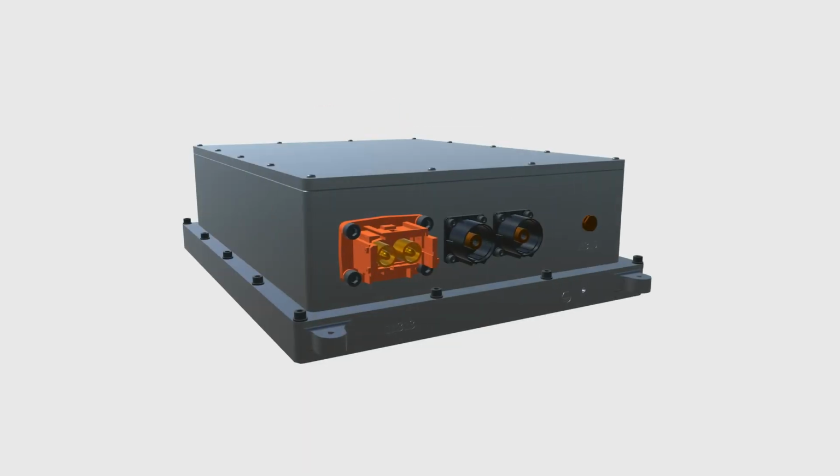Things like the battery charger and the DC-DC converter, the topologies are a bit more complex than the traction inverters. Right. So the actual silicon carbide devices probably represent a slightly smaller portion of the overall system cost. There's more magnetics, more capacitors and other componentry in the DC-DC and the battery charger that you don't necessarily have in the traction inverter. So for the DC-DCs and the battery chargers, I think the overall benefits are worthwhile, even with the increased cost of the devices themselves.